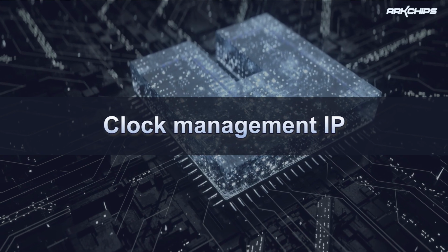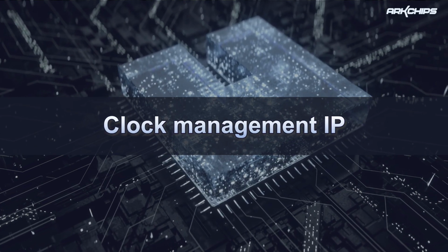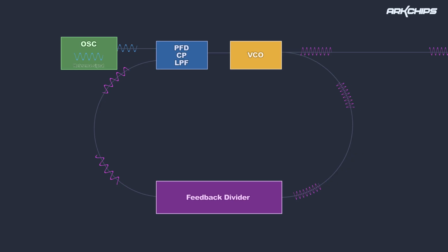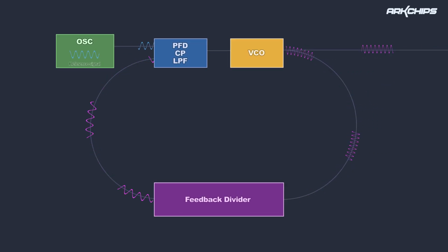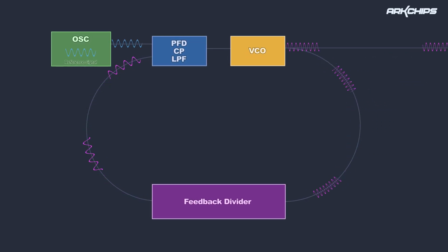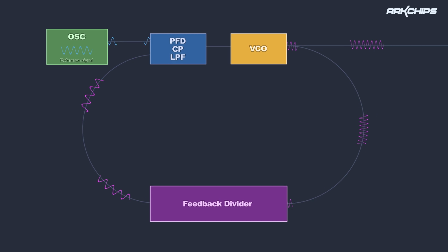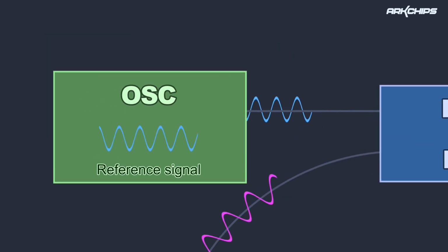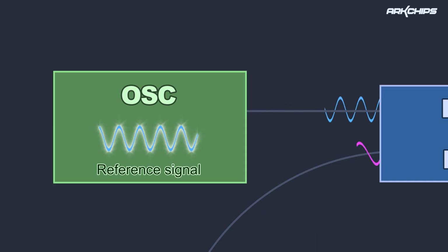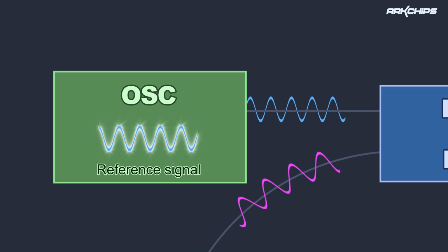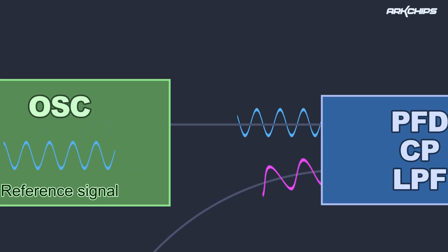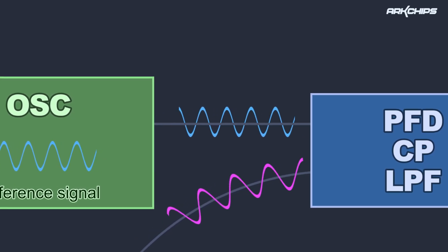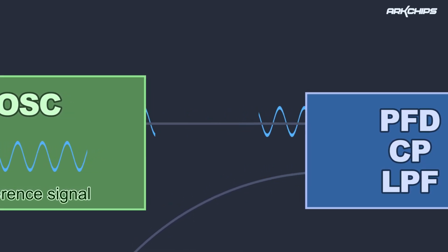Clock management IP generates the stabilized frequencies for semiconductor use. Transmitting data in semiconductor should proceed under a constant and tuned frequency. PLL IP allows tuning and calibrating the frequency. Crystal oscillator can generate frequencies with little effect from conditions such as voltage and temperature. These frequencies are stable and constant but relatively low, therefore they need to be converted into a higher frequency.